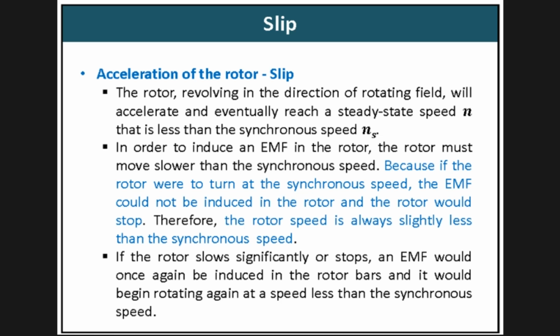If the rotor slows significantly or stops, an EMF would once again be induced in the rotor bars and it would begin rotating again at a speed less than the synchronous speed. That is what I explained.